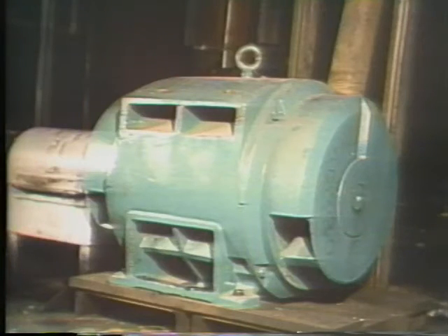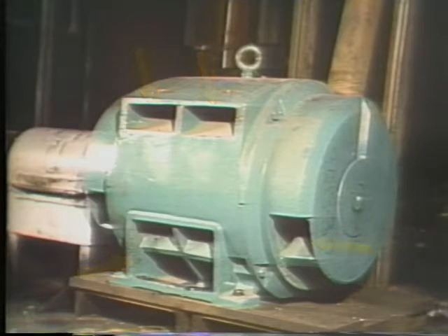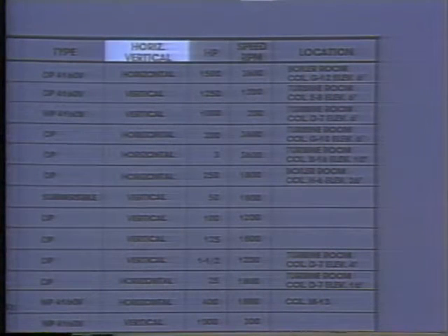There are several types of motor enclosures. Drip-proof means that the motor is enclosed, but it does have ventilation openings in it. The openings are installed in such a way that moisture dripping directly on the motor would not go inside the motor. It's suitable for use in a damp area where there is no danger of moisture being sprayed into the motor. The next column we see in the location index indicates how the motor is mounted, usually vertically or horizontally.